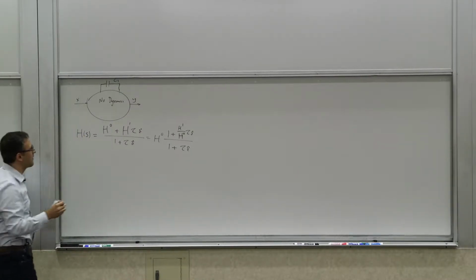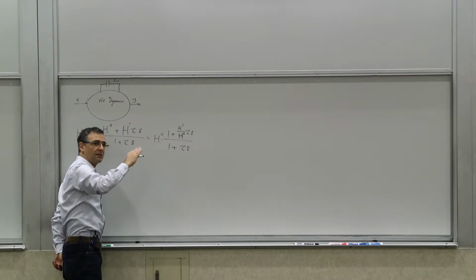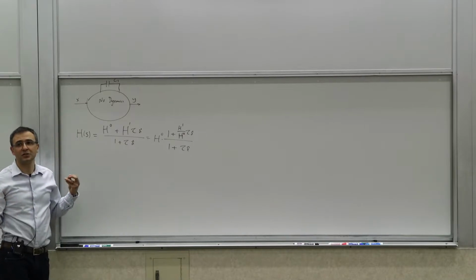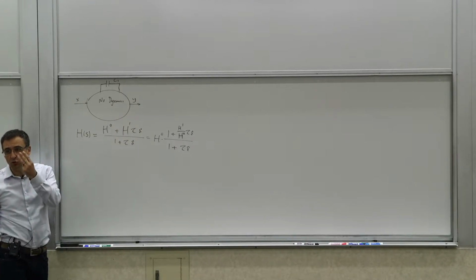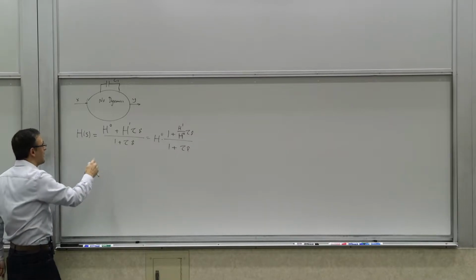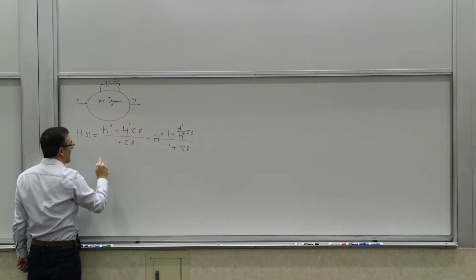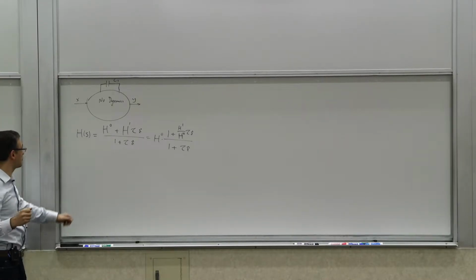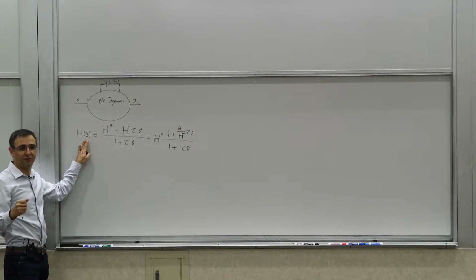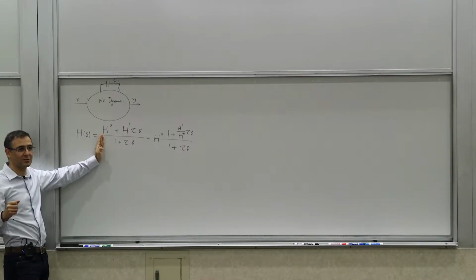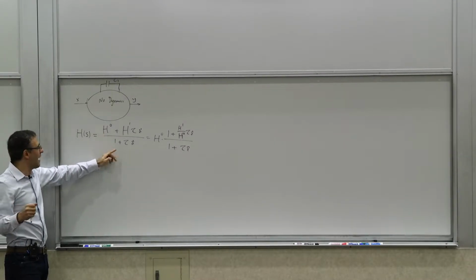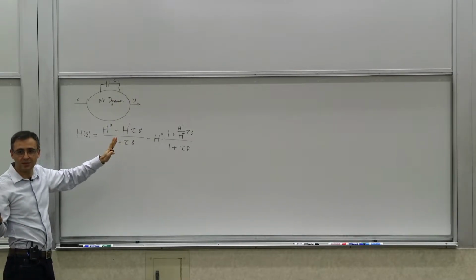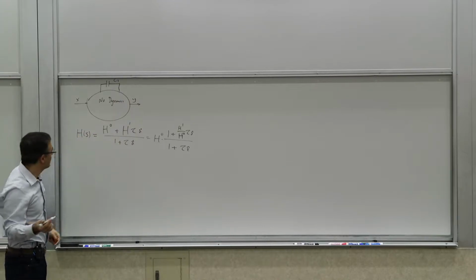We made several different parts of this, and what this does is reduce the calculation of this transfer function to calculation of 3 low frequency parameters, namely H0, H1, and tau, where H0 and H1 are what we call transfer constants, as opposed to transfer functions. This is a transfer function, but this is a transfer constant because it doesn't depend on frequency. And a time constant in this case. In general, there will be multiple time constants, as we'll see later, but this is basically a single time constant.